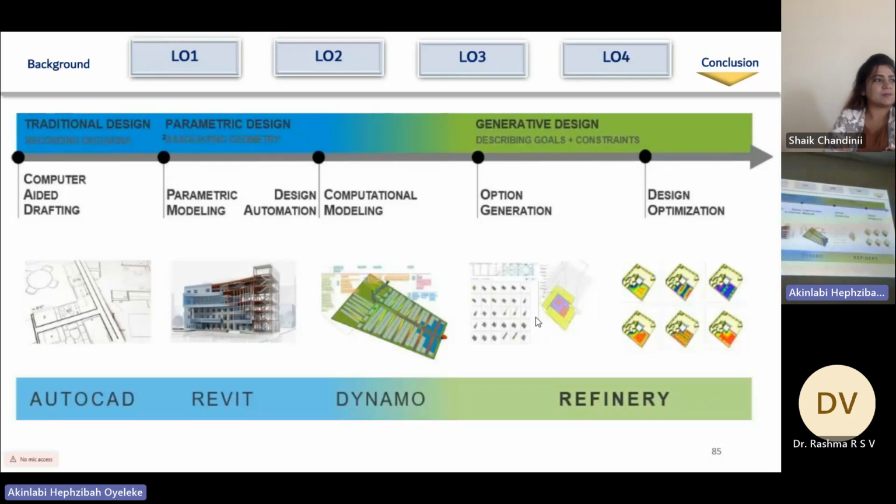Are we using BIM here? In Dubai, Revit they are submitting. In Dubai, BIM implementation, according to Article 207, says that BIM is required for 40 floors and above, or for projects that are more than 200,000 square feet. Okay, that's for complex projects. Yes, for complex projects, or for projects that have stakeholders outside of the country. So those are the three requirements.